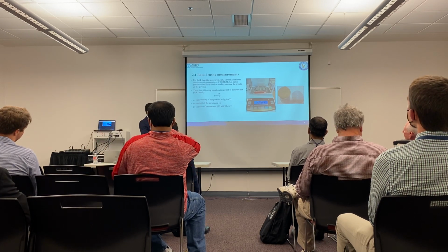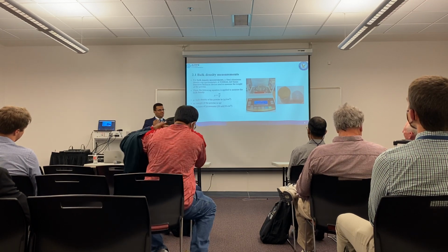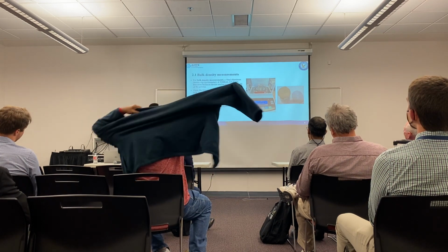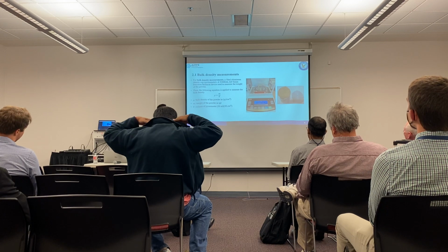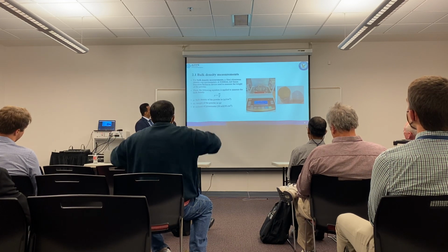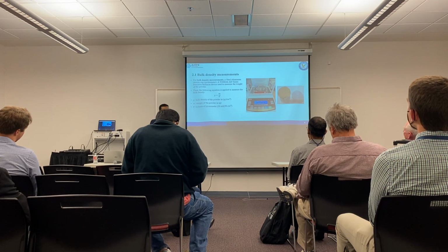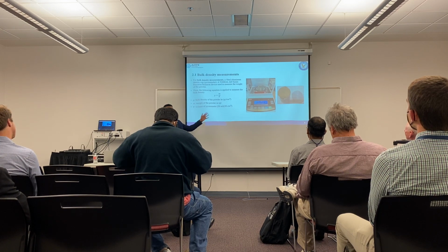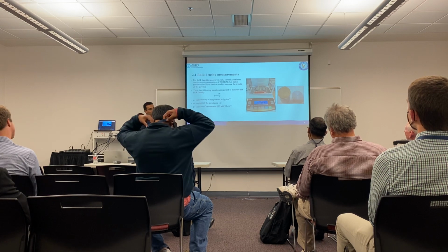After that, we have to reach an enclosed system. Then we place it on the balance device to measure the exact mass of this powder, for each powder I mean. After that, we apply the normal equation, mass divided by volume, to get bulk density. We run this 5 times for each powder to make sure of the average.